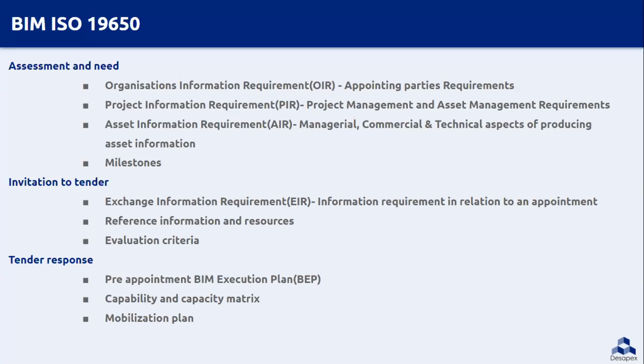Documents for the procedure involved in selection criteria is also prepared. As pre-appointment BEP is submitted in response to the tender, selection and configuration of tools, data management system, file naming conventions, model management, data exchange formats, determining communication in the project are key points covered in this stage. The mobilization plan is also recorded.